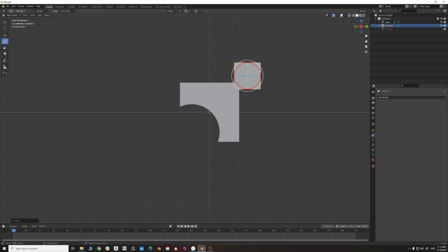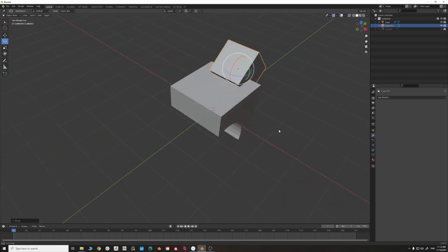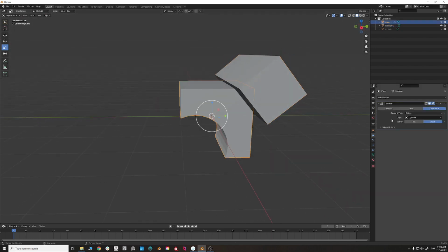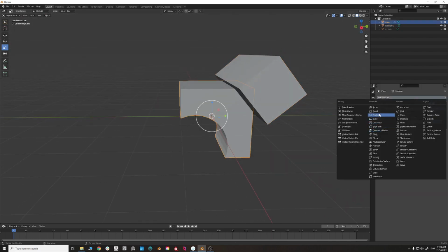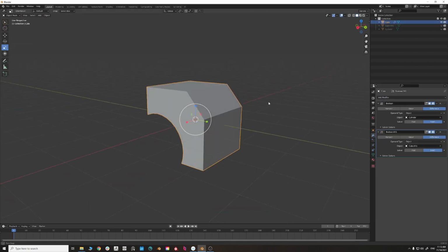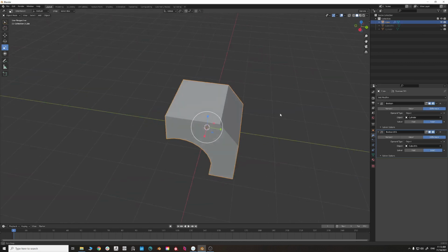Let's have it be at an angle so we can make something more interesting. Something like this, maybe. I'm going to have it scale up a bit and go through the entire model again. And right now I'm going to add another Boolean modifier. Difference. I'm picking this cube, and when I hide it, you can see, boom, it cut out the cube as well.